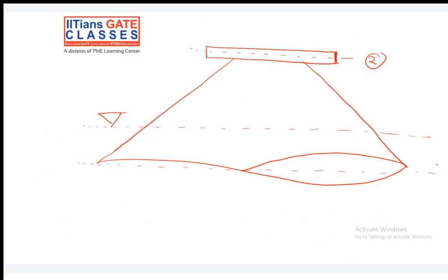So this is your third, means your datum. So 3 is datum. This is the difference between these two, Y, and this is called HS, the static head of the draft tube.